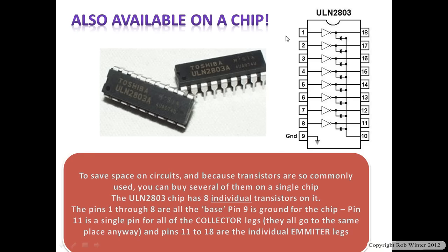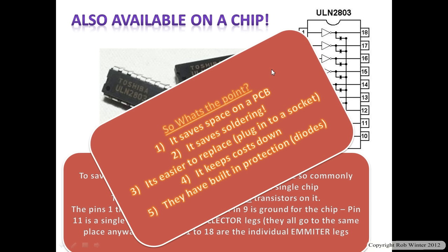To be honest, don't even worry about how it's connected up. They're not going to ask you to draw it. They might just ask you, why would you want to buy 8 transistors on a chip? And those are your reasons. It's going to save you space. It saves you soldering, because rather than 8 collector legs, you've only got 1, because it's replaced all by pin